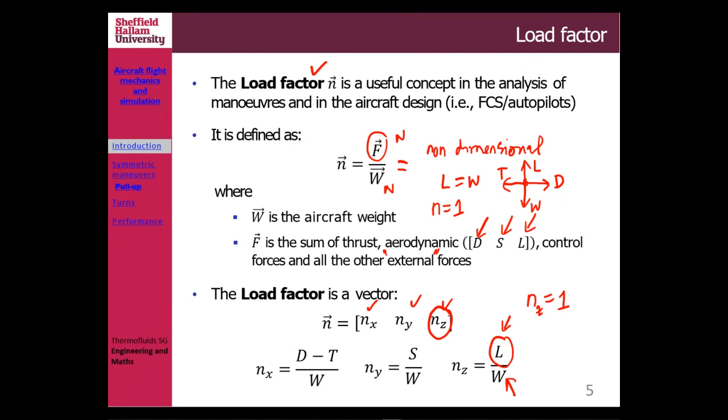But if we are designing a commercial passenger aircraft, we are talking about passenger comfort and the sustainability for human beings inside, so obviously there is a limit. We always refer the limit of the G-force or load factor to CS25, for example. Then I will show you what CS25 actually says about G-force.